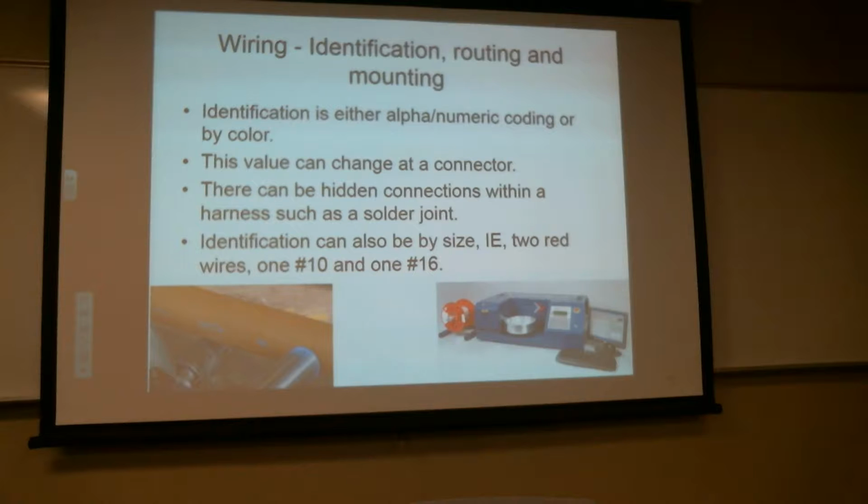The other place it can occur, and it's a little less of a problem when you're using all white wire and you have a labeling machine right there, because you can make as much wire as you need. But in the world of color coding, and I've seen this probably half a dozen times in automobile wiring harnesses, VW runs out of purple green wire. Darn. They don't stop building cars just because they ran out of purple green wire. They just grab a different color, throw it on the machine and keep on going. Somebody makes a note, as of RPM serial number, that note may or may not make it back to the tech writers. And, of course, that whole chain of process to the point that it actually gets to you.